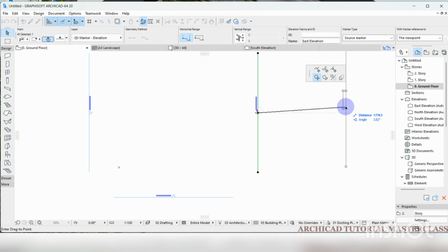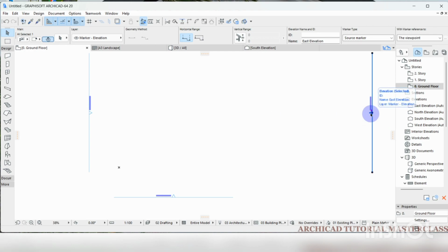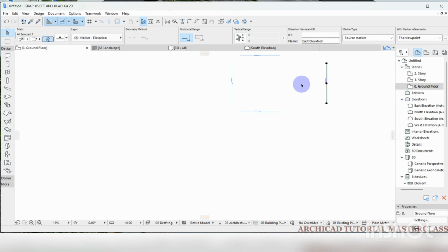When you are dragging, if you want to drag it, let it be horizontal, let it not be slanted. You can see the angle and the distance, so you can always hold your shift. This shift will help you to move it without moving it other than 180 or 90 degrees or 0 degrees. So you can say I moved it this way. When you move, you click, and you can remove your shift.